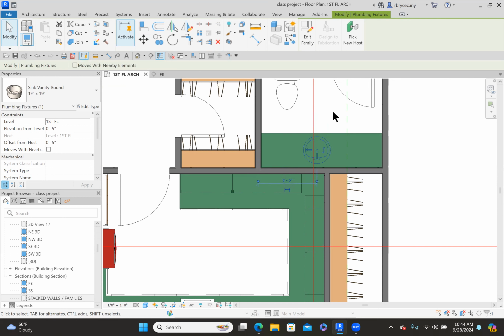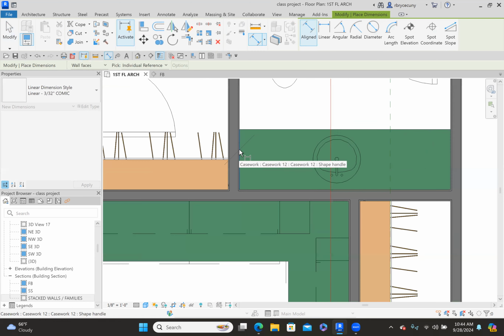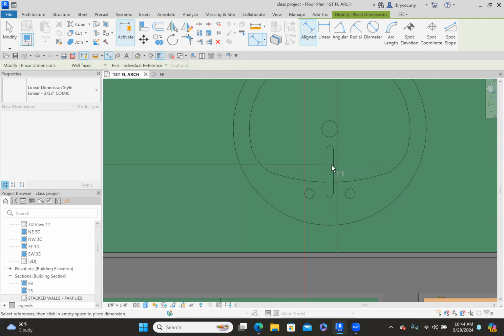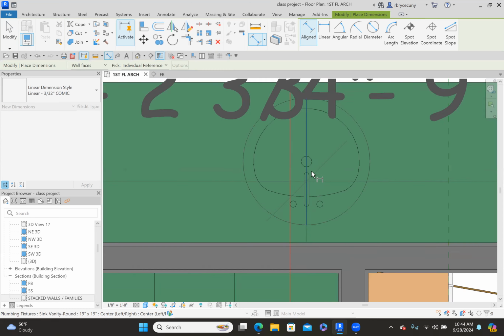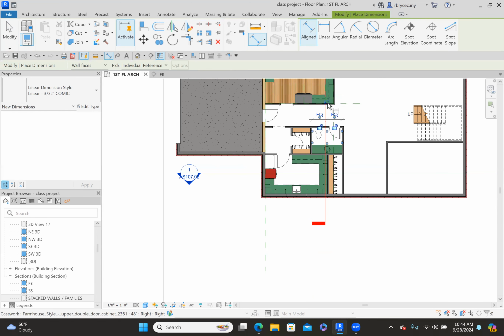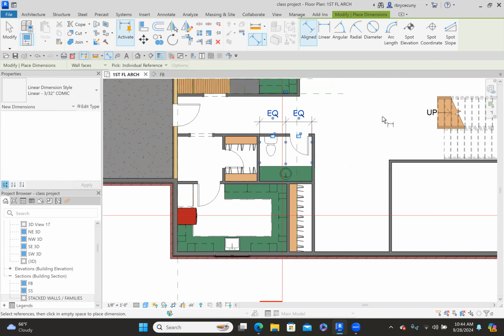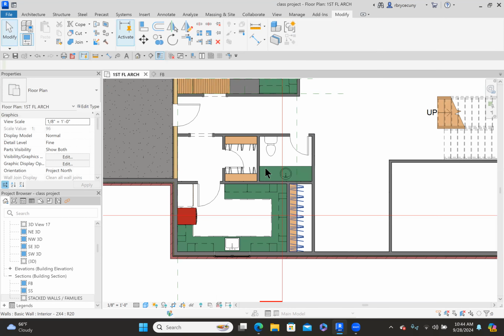Looks good right there. Double check to make sure that it's centered, exactly centered. So I'm going to dimension to, you don't necessarily have to go in order with your selection. So I'll just click it right there. I'm looking for the equal button. Okay, it's equal. If I hit, then I'll just delete it. It's going to say unconstrained, which is fine.